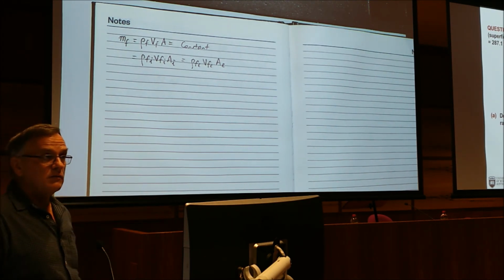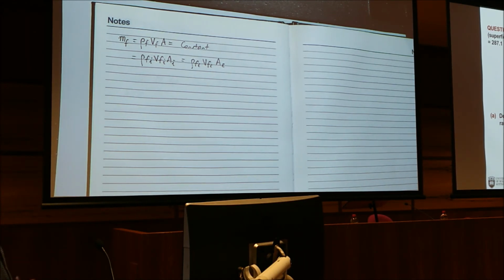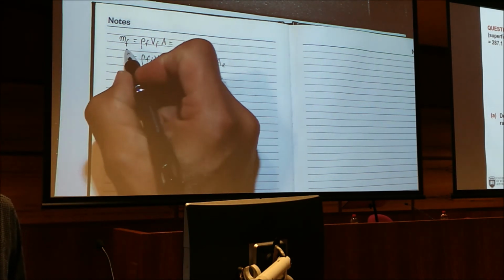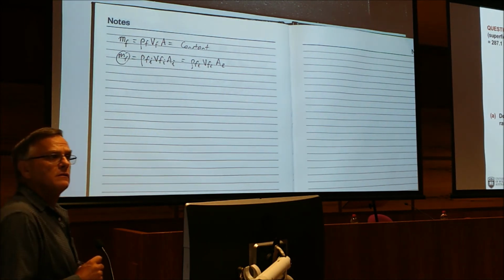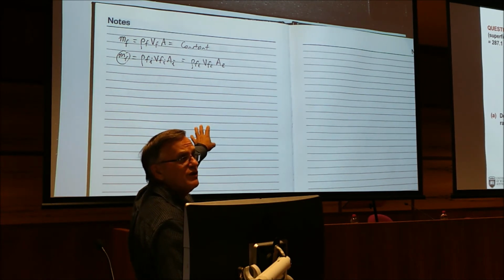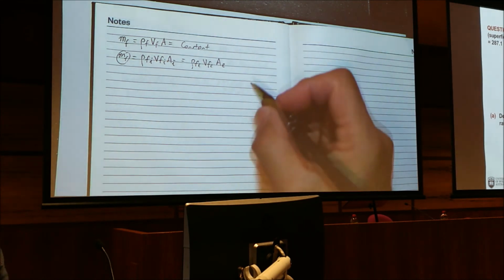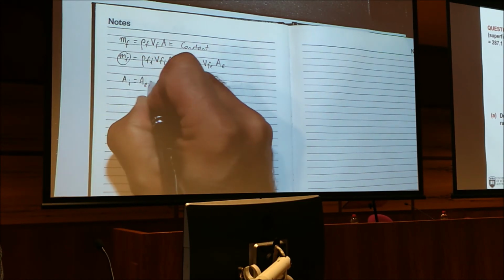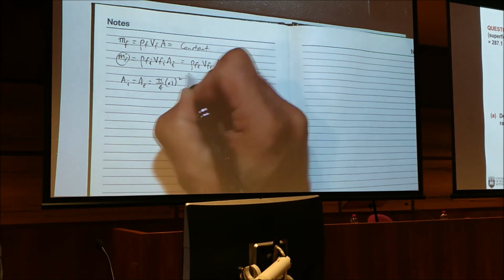That's from that previous slide, all right? That's the continuity equation. So the question asks, what is MF? That's what we're trying to find. So we've got to look through these equations. This equation, what things do we know? Yeah, we know the area. So we can say separately, AI equals AE equals pi on 4 times 0.1 squared.